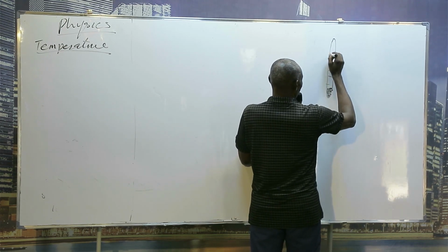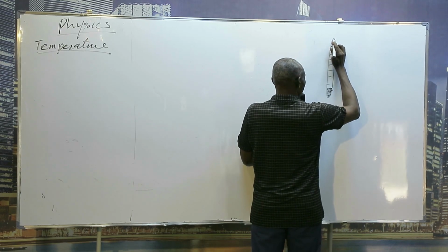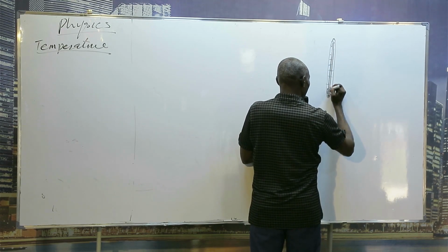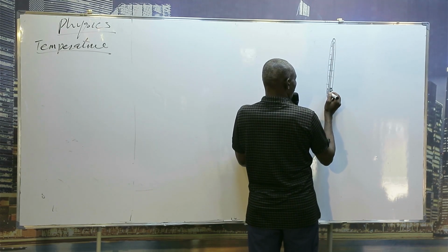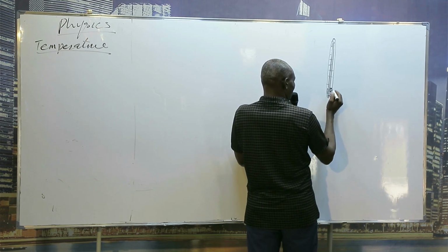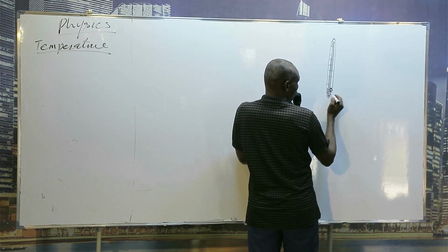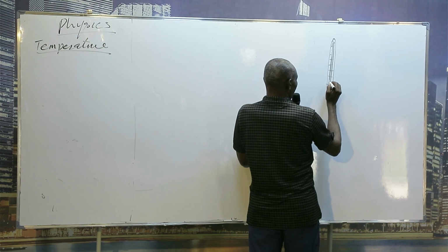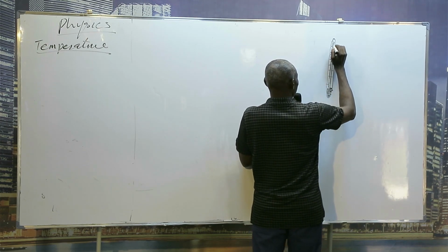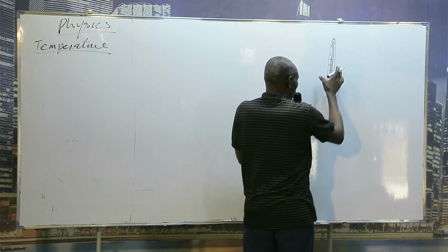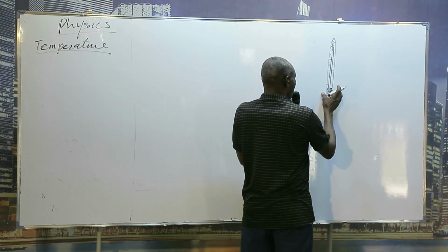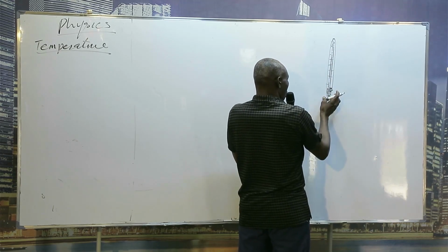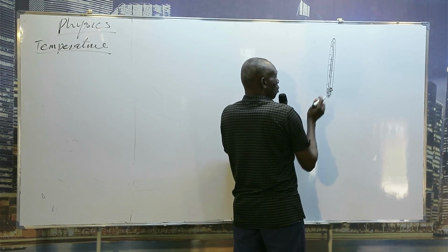This is the scale. And right here you have a uniform bore inside. So this mercury or alcohol, whenever this is inserted in any particular temperature environment, will start moving up. So this thermometer has the bulb, scale and stem. The stem is where you read, but the bulb is the part that contains the mercury or alcohol.